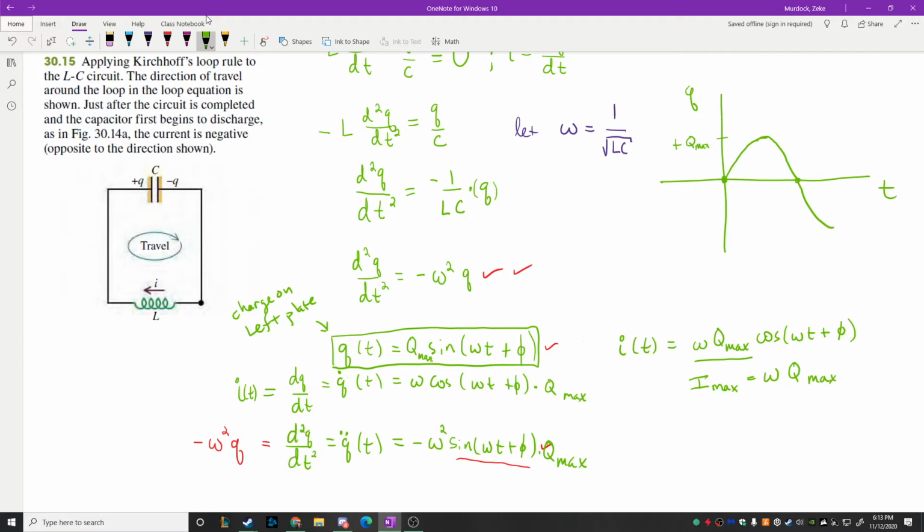And then the charge starts to go negative until eventually you've reached the maximum negative charge that you can hold on your plate. Then that process repeats itself, heads back to 0, and we go through one more phase again. The time that whole thing takes would be considered the period, and what that immediately shows you is that what's happening in this LC circuit is a type of oscillation of charges.